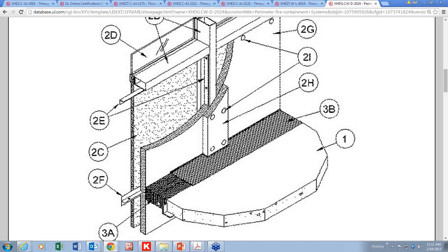If it were a concrete block exterior, this curtain wall assembly could actually extend all the way out to the exterior skin of the building, making it continuous. However, then in the moisture design part of it, there would have to be weep holes through that assembly, which wouldn't be all that great for the fire resistance assembly because the weep holes may cause a problem. There may be some tested and listed systems. Check with the manufacturers on that.